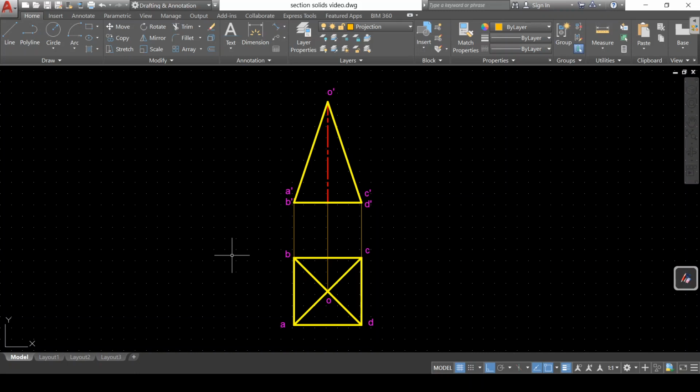So in that case we will position it in this way so that the cutting plane will cut either this way or this way. Any way is correct. These 2 points will get here and 2 points will get here, and this should be 20 and this should be 40. So to get the position of the cutting plane, let us draw the true shape first.